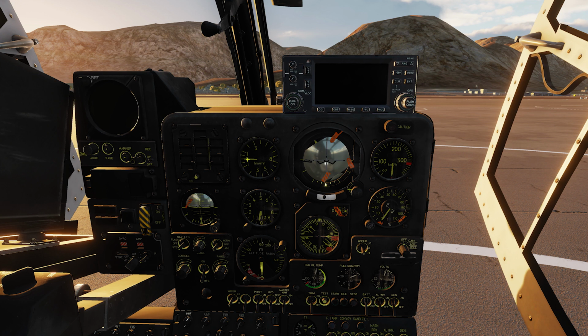And as you may recognize, all values are in meters. So it's a French aircraft, so also the airspeed indicator is in kilometers per hour, and also the altitudes are in meters or meters per minute. So this instrument has meters per minute, and you can see it is in hundreds of meters. So if you continue to the right, we have our artificial horizon. We can't uncage it right now because the aircraft is not running. The artificial horizon shows us our movement in space. So if the nose is down, if it is up, if the aircraft is tilted to the left or to the right. So we will take maybe a closer look later on in this tutorial.